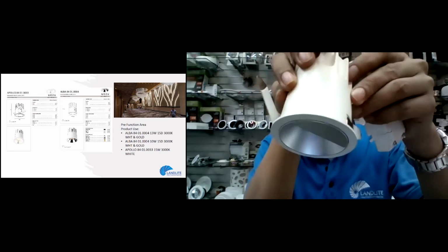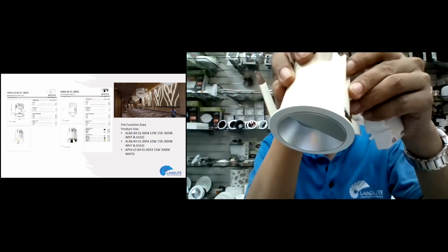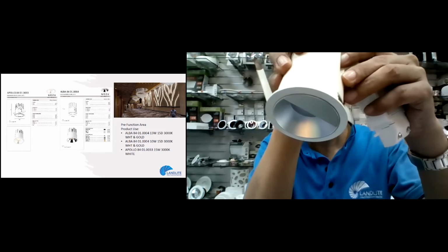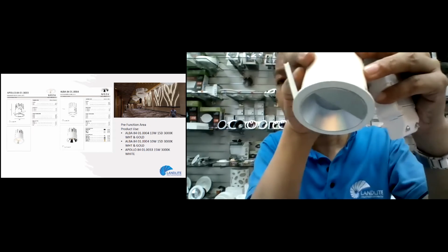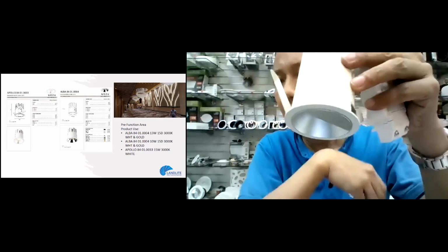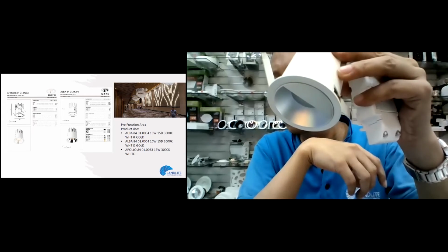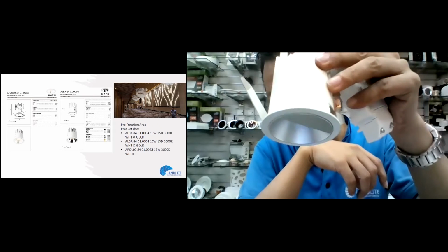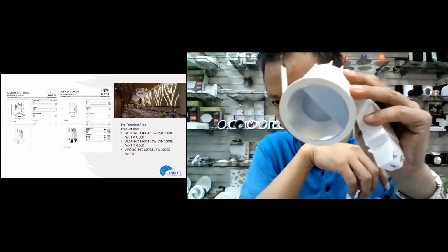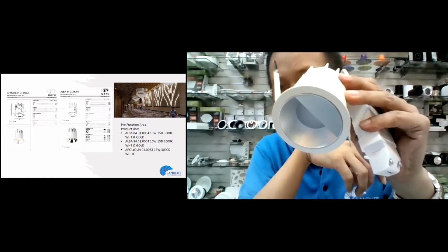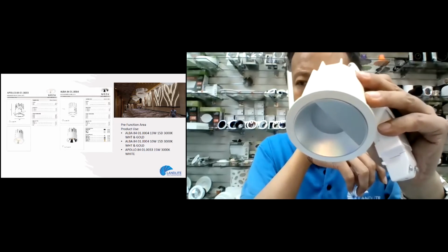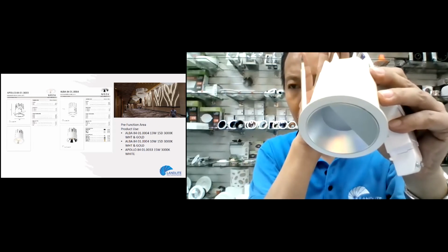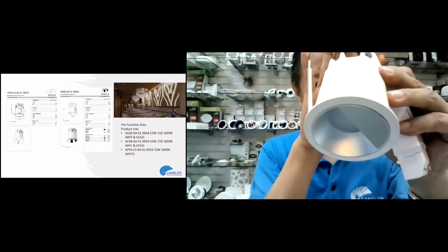Why do we need a wall washer? The wall washer tends to give a linear wash, not that kind of look. So, the wall washer gives a linear wash. The wall washer is very good, particularly for pictures and portraits. It's good to position the wall washer exactly at the painting. So, these are what we call wall washers.